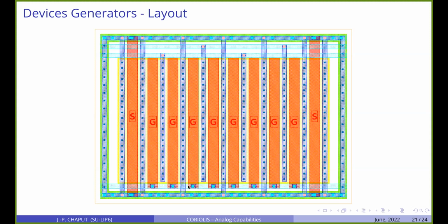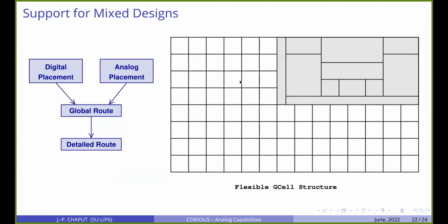There are 2 transistors here, 2 interleaved transistors. And the interleaving is just ensured by how you connect to the different drains. We have 2 drains here, and it's easy to choose to which drain we connect. And by changing that, we can completely change the functionality of the device. So this is the layout that we chose to implement. But if you change the script, you can change that shape completely.